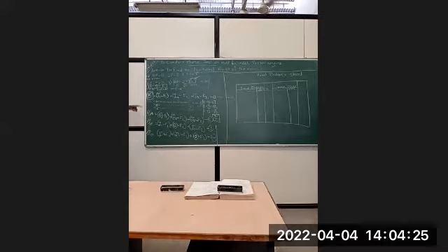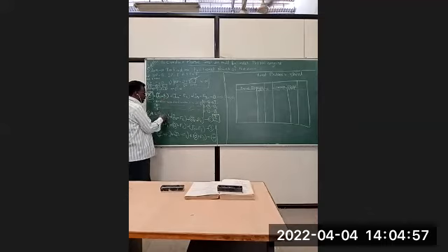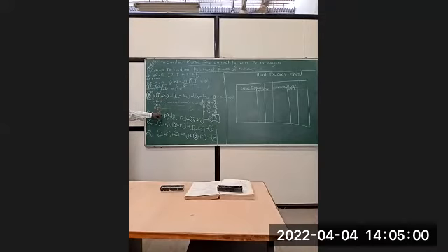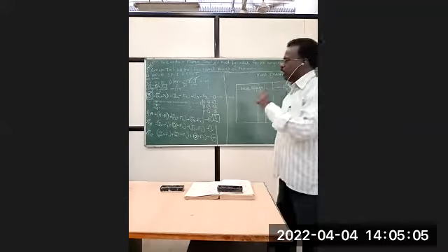Now, if F1 minus F1 is to cancel out, this is F1. If we want it to cancel out, then we have to ensure that here also the engine is running at 2000 RPM, here also it is running at 2000 RPM, here also, and here also. How? Because here, see, indicated power is 0, but obviously the frictional power is there. And the frictional power will get cancelled out when the frictional power here and here is equal. And when it is going to be equal, when the number of rotations per